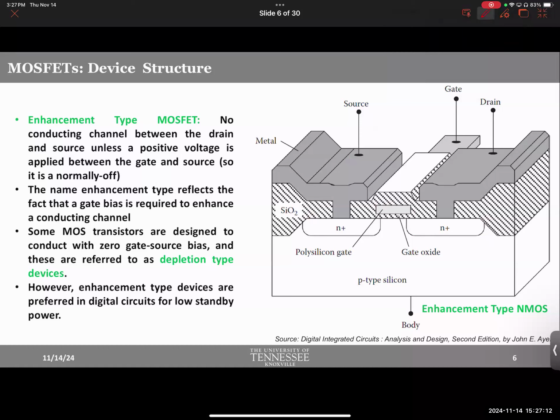So you create that at the process level. You create metal. This is metal. So you create a connection between metal and semiconductor, and you ensure this is ohmic contact or almost close to ohmic contact. And now externally, when you apply a voltage, you just connect the wire here to the metal. You don't care. You're connecting metal to metal. No Schottky, no ohmic. Like, it's always good. You're not connecting metal to semiconductor anymore. Are you all good? Okay.